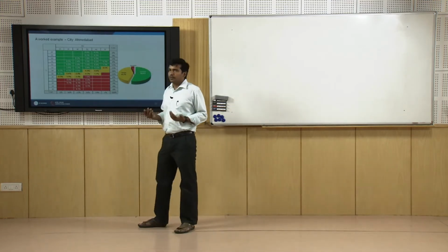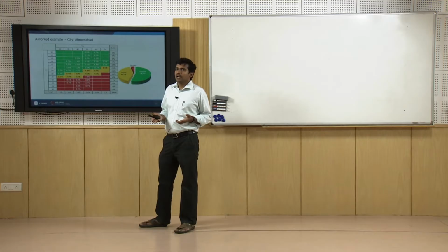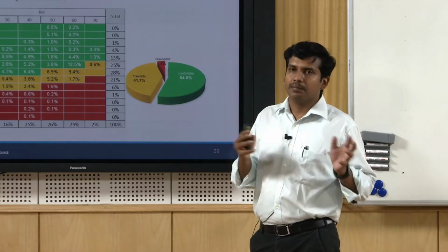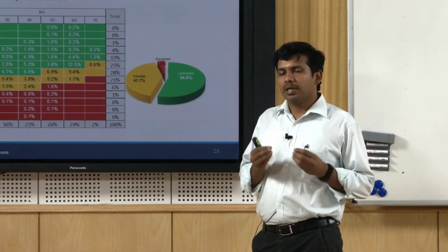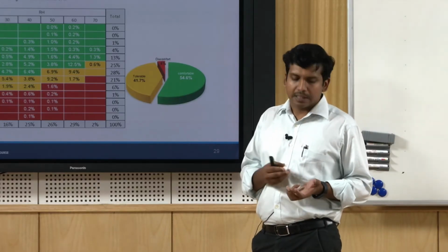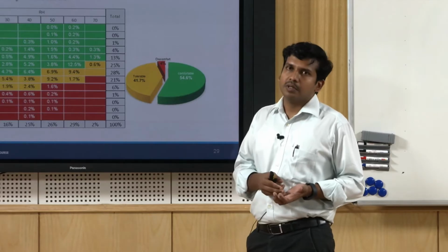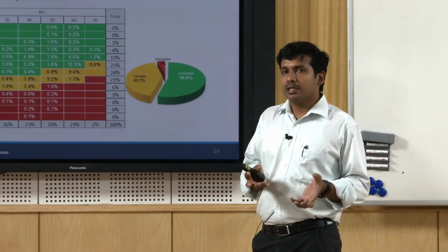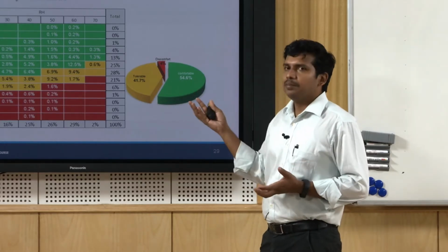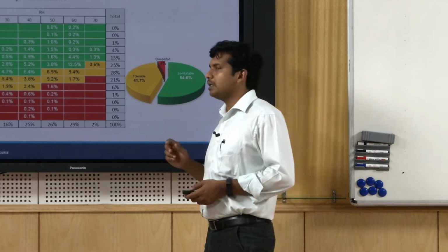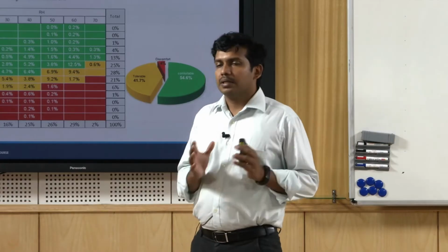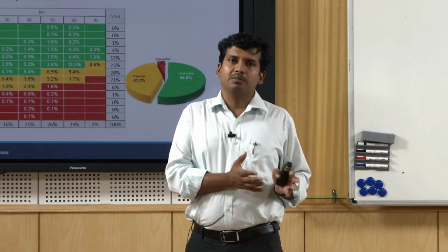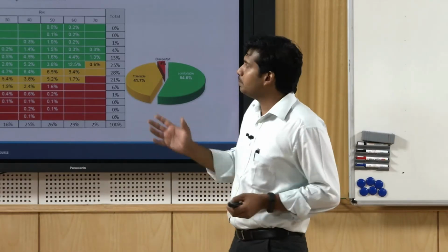A typical example which we worked out, an interesting case: we know that these boundary conditions exist, so how do we really report? Say you want to measure your own classroom or house and report whether temperature, humidity and air velocity are okay or not. A minimum climatology lab will have sensors for temperature and relative humidity as well as an anemometer. With these quick handy tools you can do simple experiments and report, as per the National Building Code, whether comfort conditions or acceptably warm conditions exist or not. A simple way of reporting.